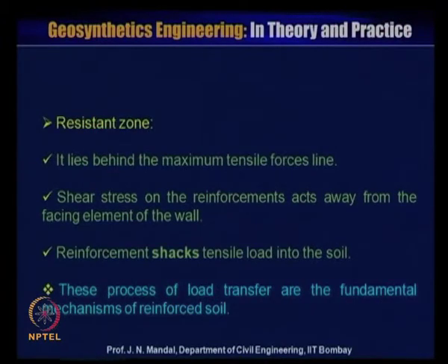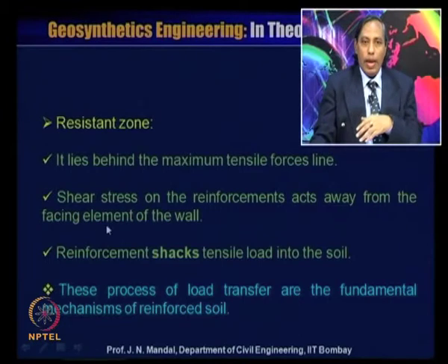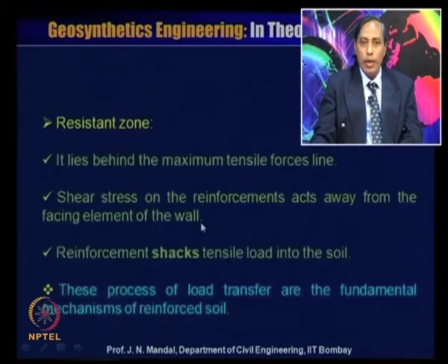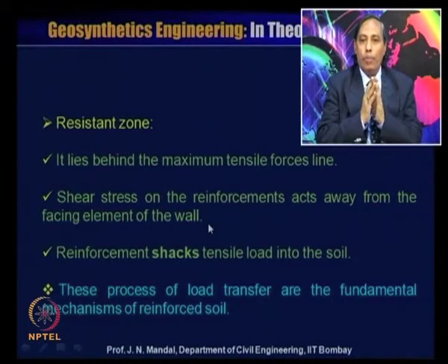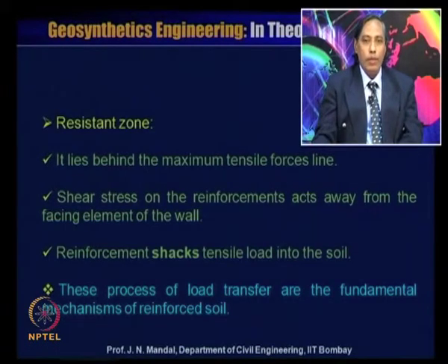In case of the resistance zone, it lies behind the maximum tensile force line. You can see this is the maximum tensile force line and it lies behind it. And the shear stress on the reinforcement acts away from the facing element, and the reinforcement sets tensile load into the soil. So, this process of load transfer is the fundamental mechanism of reinforced soil.